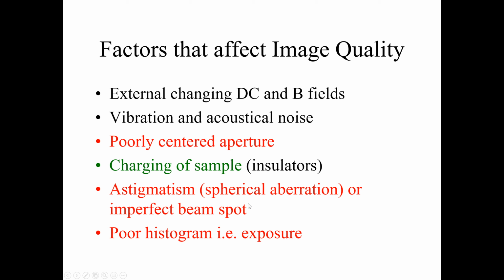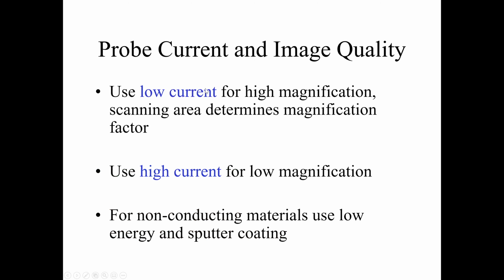The most overlooked image quality impairment I find is the operator not understanding how a histogram works, and when you get into the auto mode where you're just clicking buttons and really not knowing what you're doing. I find a lot of the students that use the microscope don't have any background with standard photography, and this last one is very, very important if you present data based on a backscatter image.